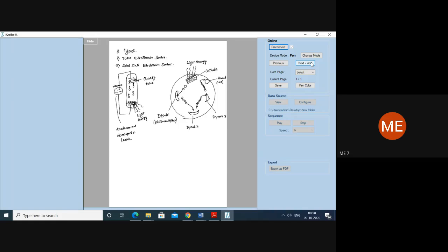Now finally, the electrons which are collected at the anode constitute what is called the anode current. The anode current developed is proportional to the light intensity. The basic concept of light intensity is that some electrical property is going to change, that is, the value of the current is going to change depending upon the application of the light. Now, this is about the photoemissive sensors.